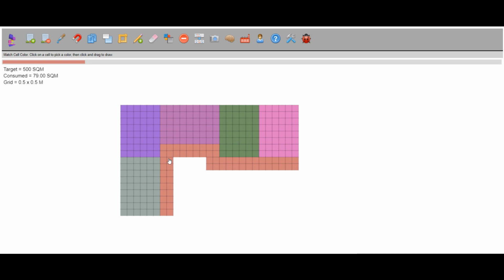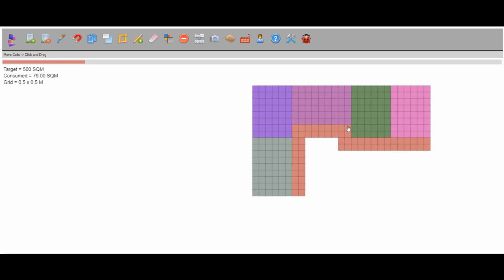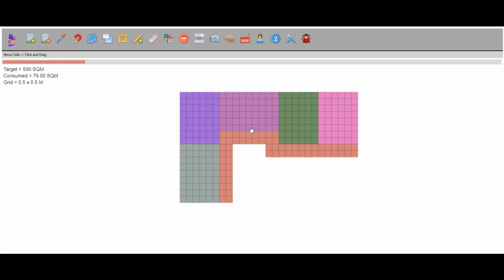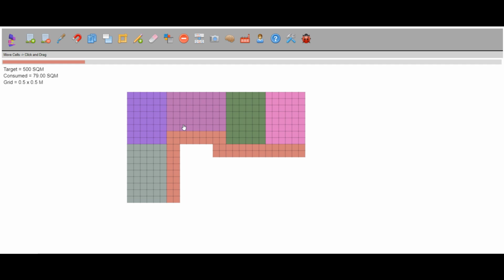So many times what happens when you shuffle, or many times you want a bigger drawing, that time things might go off screen, so you may want to reposition. So there is a move cell command here beside this copy paste, so you can click anywhere and just move this entire space somewhere. So everything which is happening, it will always be happening with the grid size. It will always be within a scale of a grid. That could be changed at the initial project stages or later project stages. I will explain that in later stages.